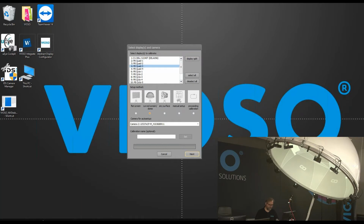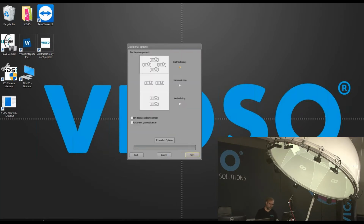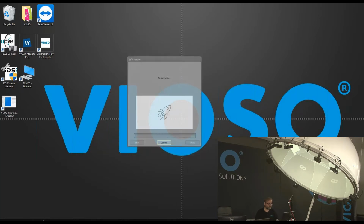So you select the projectors to calibrate. The first step is to select the projectors to calibrate, which kind of screen, curved screen or dome, and the camera. So this is the fisheye camera. Provide a name for this calibration, which is a bit important because this name will take a role when you export to Pandoras Box. The arrangement of the projectors, in this case, is not a strip or grid, it's something else, so we call it grid and arbitrary. We do a new scan, and the calibration should begin.